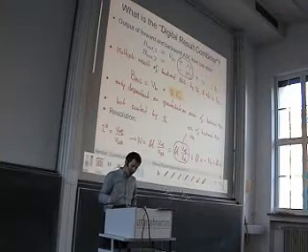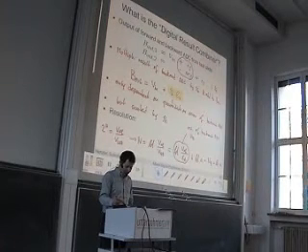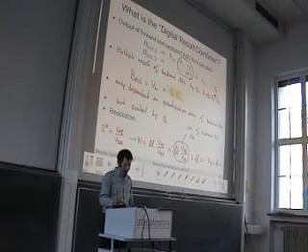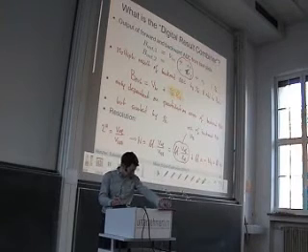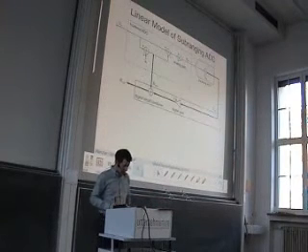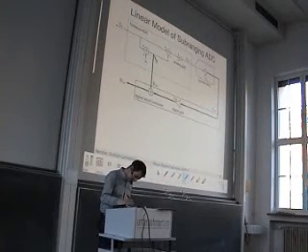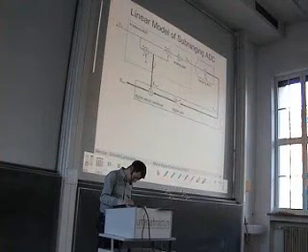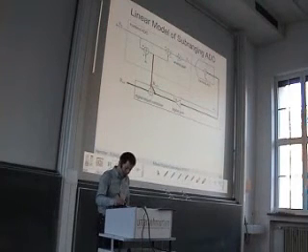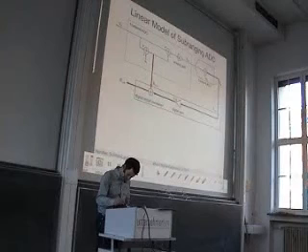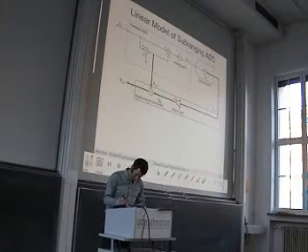Here you can see how we can combine these two results. In order to do this, we multiply the second equation by 1 over A and add it to the first one. So how does this look in a circuit? In the circuit, it looks like this. We take, in the digital domain, the first output signal. So this was the first equation. And we add it to the second one. However, the second one is scaled by this factor of 1 over A.